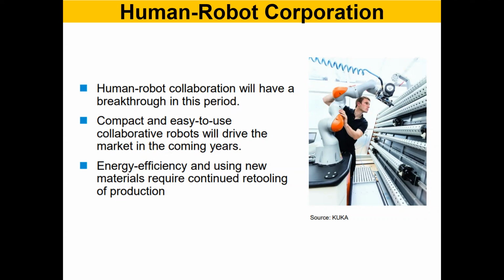So even the material you're going to use for the robots is going to change. You can see it over here, right? This is different from the looks and feel of industrial manipulators. Not only the material and the appearance, the control systems are also going to change to what is called impedance control, hybrid control, compliance control, like that, right? So that it will be not only position control, but position and force control together.